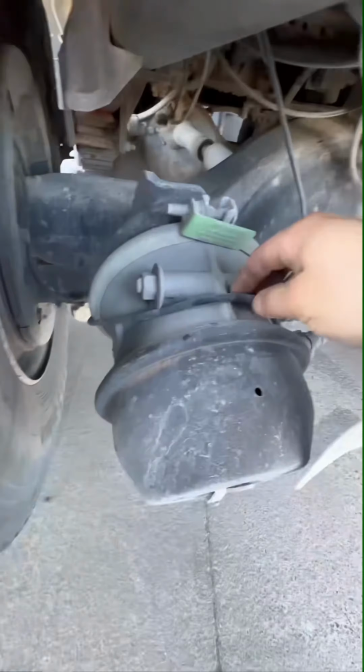Now here's another tip. When working on European cars that take a lug bolt instead of a lug nut on the wheel, it's a good practice to use these stud pin hangers. These are made by Tool 8. Tool number is 65180. These help you safely remove, install, and center the wheels on the hub.